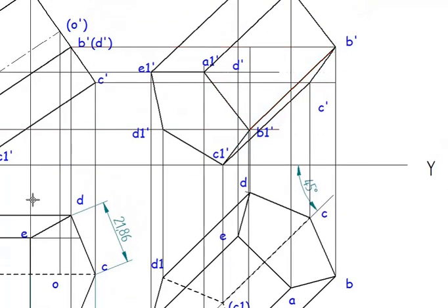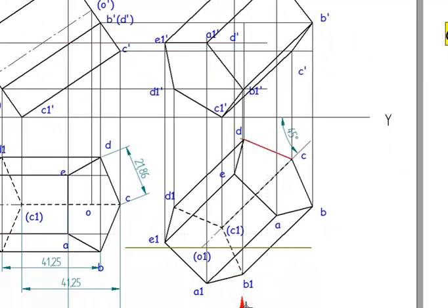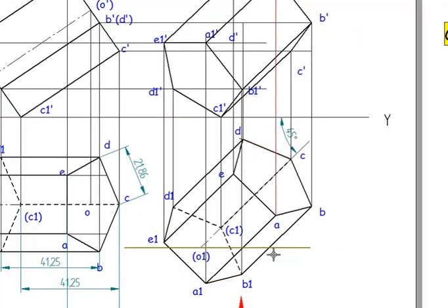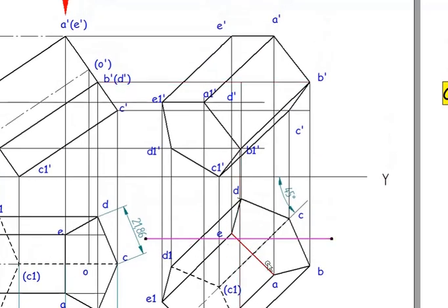Now you need to see the farthest point. So the farthest point is D point. So it's an imaginary line. The first farthest point is D, the second farthest point is C, the third farthest point is E. So I need to go for the first farthest point, which is nothing but D. Hidden lines from the D point: it is moving to the E point, D to D1, D to C.